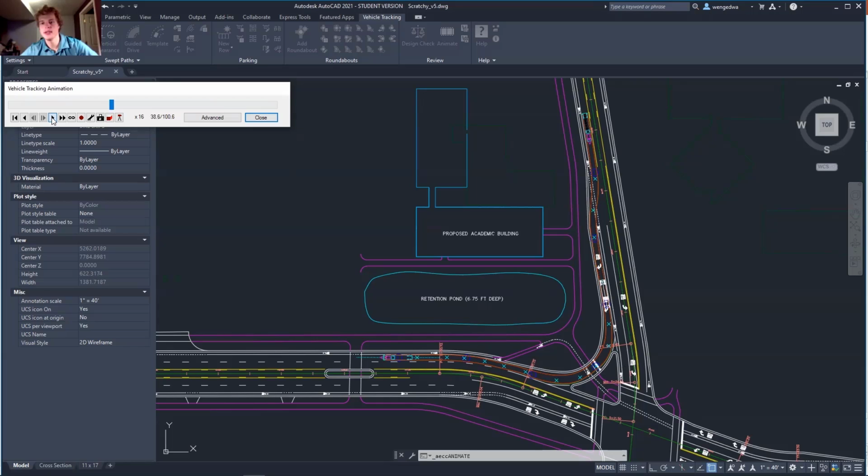As we can see here, we have the WB-40 truck coming through this slip lane, and this confirms that it can indeed pass through the lane without clipping any corners. We also tested each of the other curve radii, and it ran smoothly through. So we have a nicely designed vehicle for the maximum vehicle that's going to be seen on this roadway. This is a confirmation check.